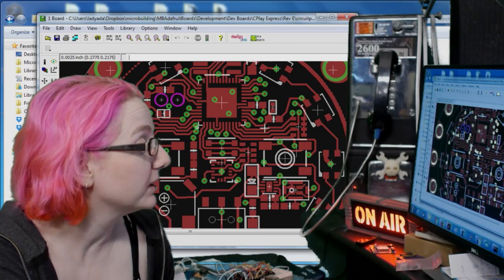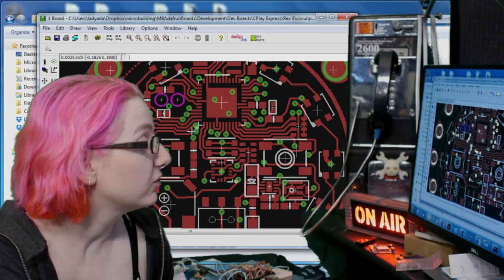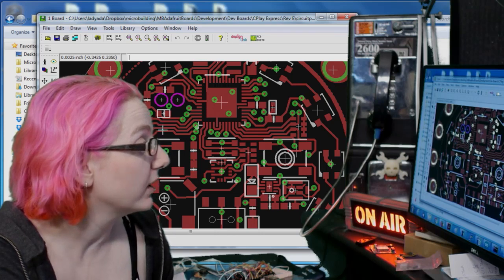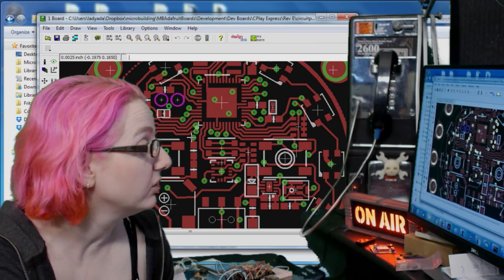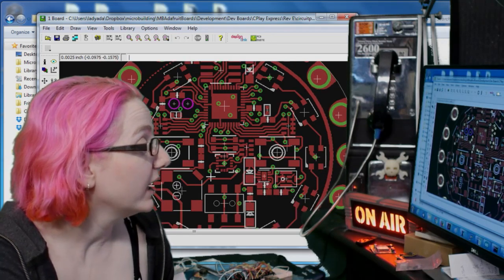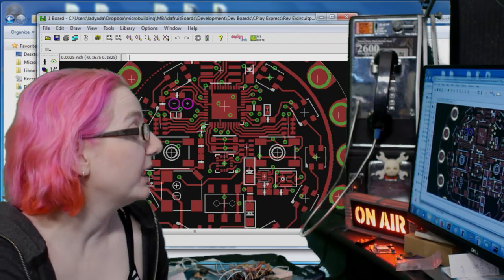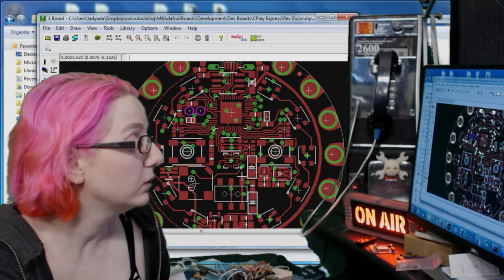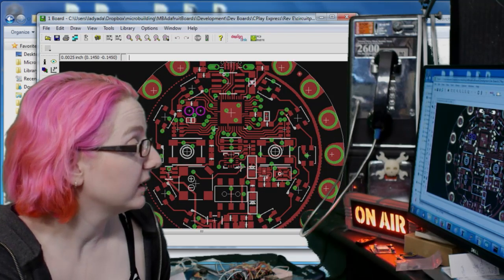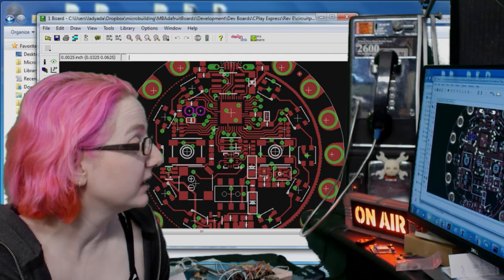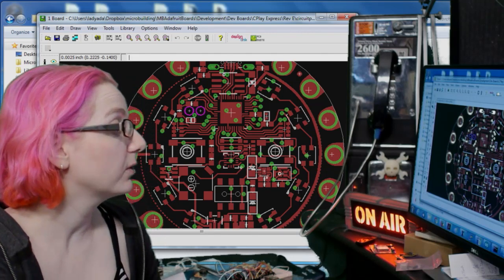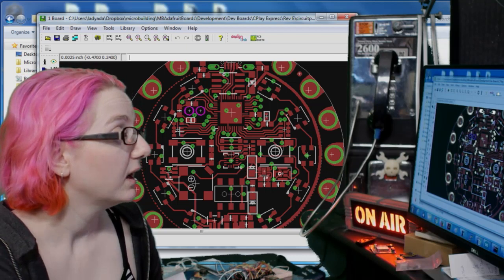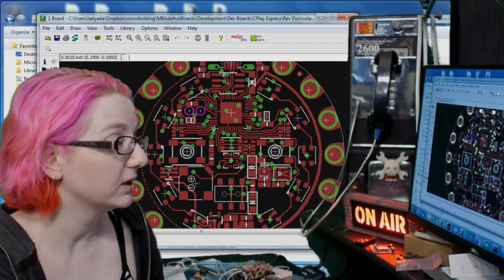I can move the buttons up a little bit maybe, or I can just change the routing around, because I don't have to route around these pads so much. And what I would like to do is make some space so that I can get these 2 LEDs. These are IR LEDs, and maybe get them spaced a little nicer. These are for infrared receive and transmit. And I'm kind of running out of space down here. It's getting a little cozy, I guess.